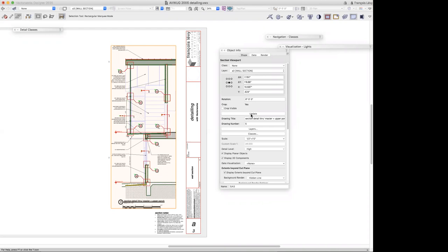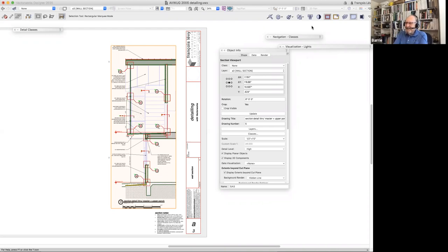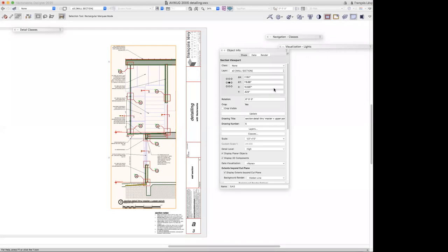But again, at the time, this was years ago, he would have to go in and manually mask all of his doors and windows on his reflected ceiling plans. And it was important to him, and so he did that. But now he could just swap out some 2D geometry that essentially hid all of the window information directly from the plugin object, and so he would never have to do that again. And there's low, medium, and high, and those settings are set on a viewport by viewport basis. So if for some reason you need to mix low and high detail within the same viewport, then you're better off just annotating that in the annotation space, because of course you can draw in the annotation space, and there you go.